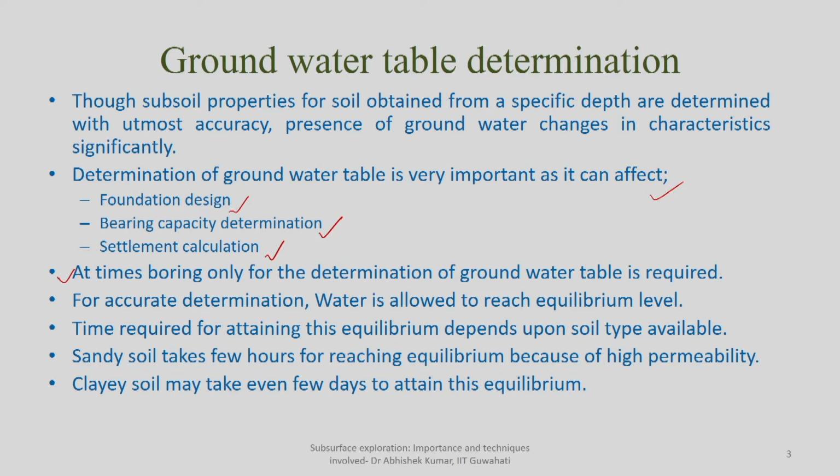That will give you a proper indication, whether for sandy soil or clay soil, that the groundwater table has reached its equilibrium position. Because if you do not wait for equilibrium, most of the time you will end up underestimating the groundwater table, reporting it at a much deeper depth than what actually is the depth of groundwater in the surrounding region.